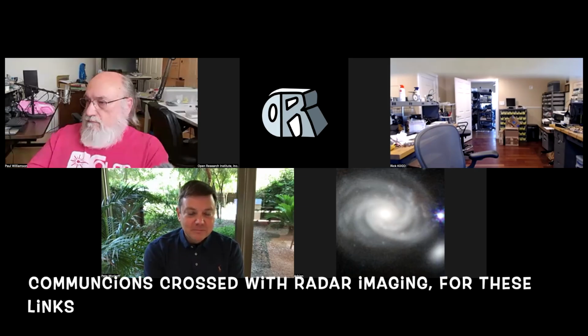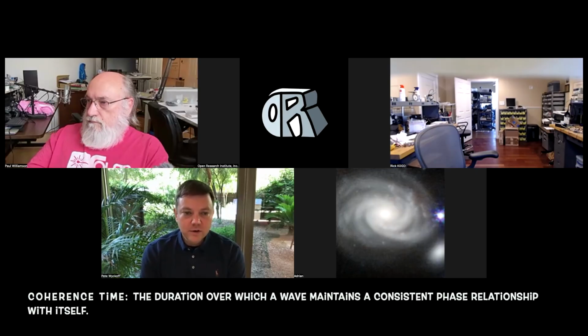Because at the end of it, you're getting into delay-Doppler characterization of channels, and it's almost getting into radar imaging of the moon to make these predictions. That's a couple of the harder problems that after part two we'll have to think about how we might do. The exciting news, though, when you look at delay-Doppler and things like OTFS, you end up with longer channel coherence times than you normally encounter.